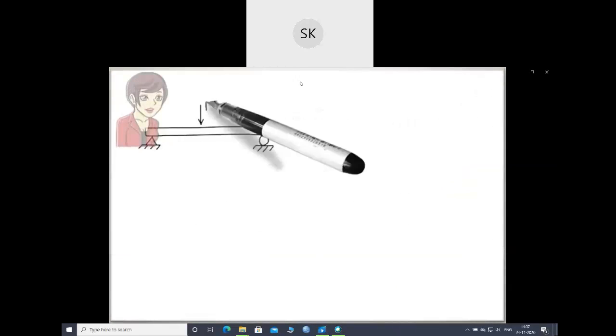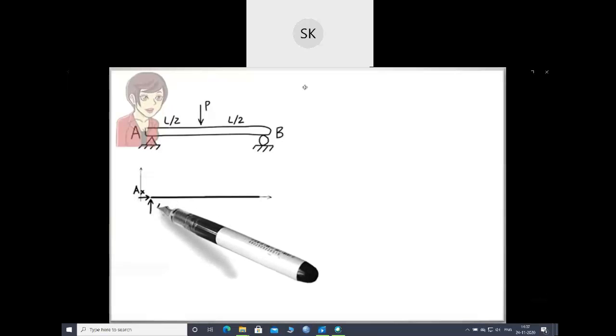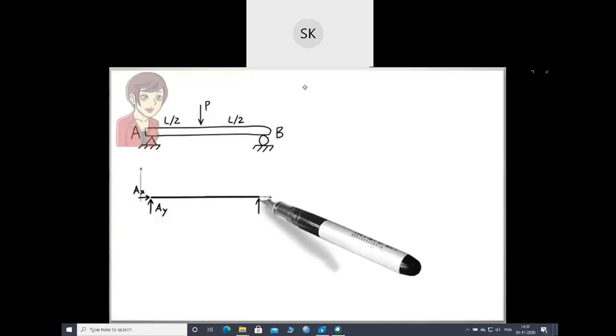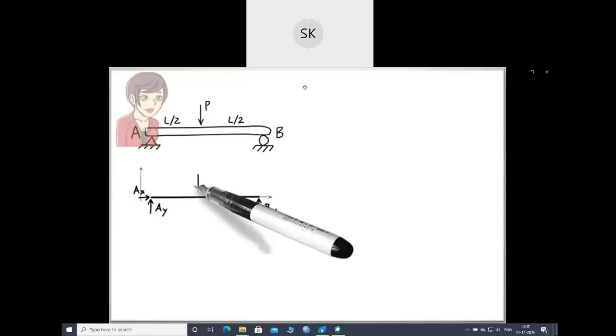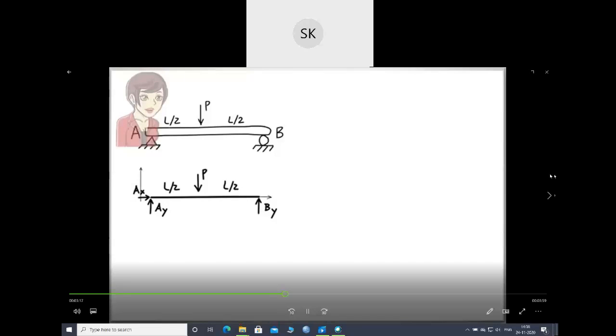In order to analyze a beam, it is customary to draw a diagram called the free body diagram, showing the applied and reaction forces and their locations in a Cartesian coordinate system. Note how each unknown force in the diagram has been uniquely labeled. The free body diagram helps with the correct formulation of the equilibrium equations.